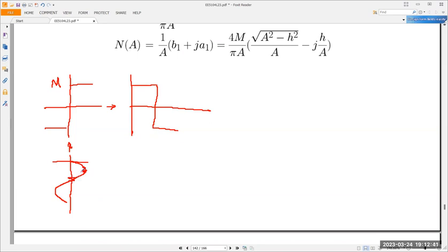You see, here it will still be positive m, then suddenly here, because of noise, it becomes negative, so you come to a negative m. Then because of noise, you jump back to positive, so you go back to a positive m. Then because of noise, you go back to negative m. And then you continue with negative m. So every time you have a zero crossing because of the noise, crossing over from positive to negative, you will have a chattering, zap, zap, zap, like that.